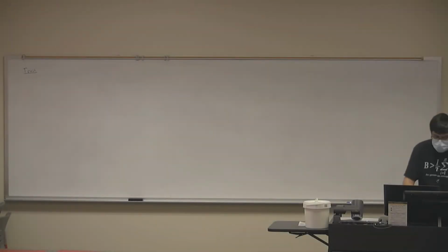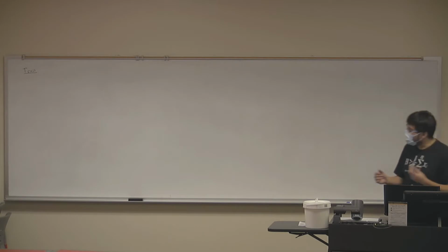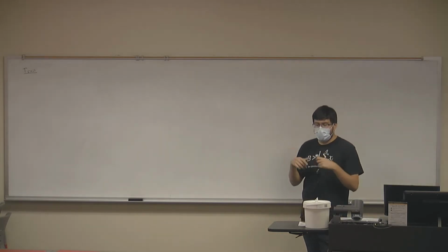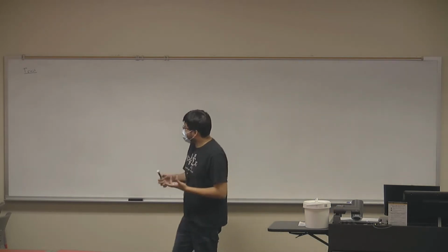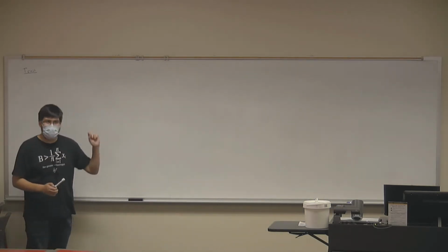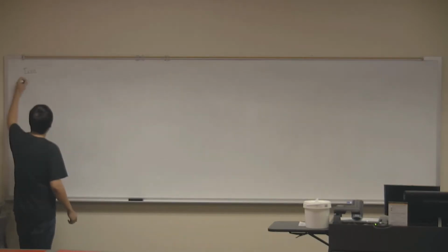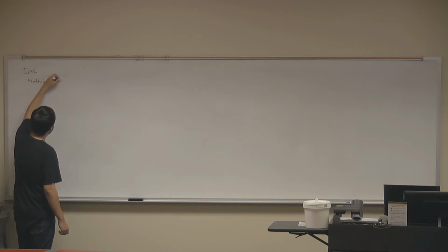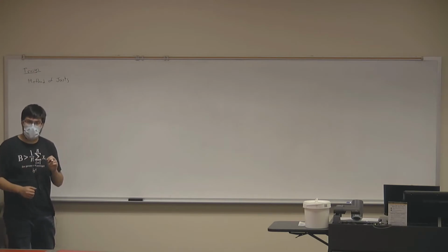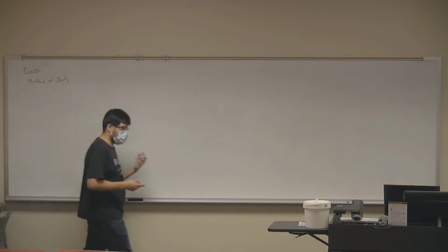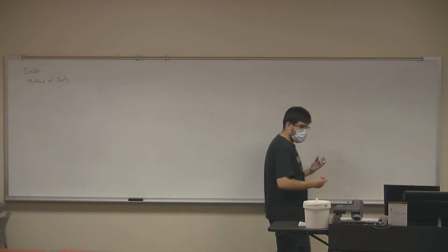All right, so in the previous week, we talked about solving trusses by looking at the individual joints and drawing a free body diagram about each joint, which is what I just talked about, right? That method, where we looked at each joint individually, is called the method of joints. So the method of joints is simply the method where you look at each joint individually, draw a free body diagram at each joint in order to find the forces.